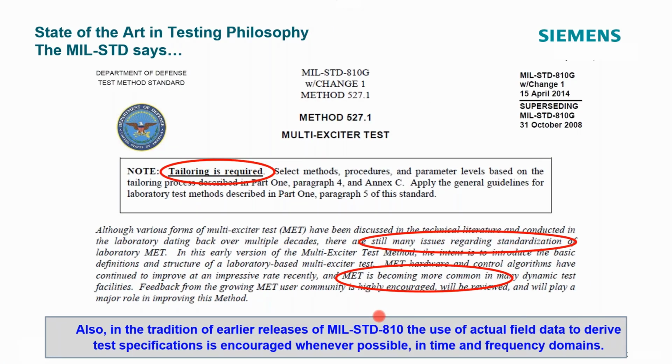The very famous MIL-STD-810 government document also advises to be as close to reality as possible. In fact, they even make the statement that tailoring is required. And tailoring implies that you want to go out and measure in the real environment and characterize it, either through frequency analysis or time data analysis. You want to bring that information and tailor your test to accommodate those kinds of responses in the real environment, in your laboratory, to again replicate the real operational conditions.